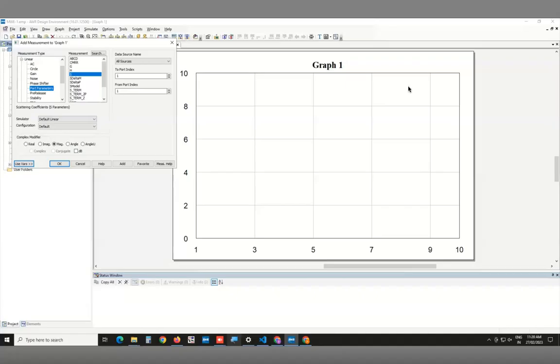Right, this is the same gamma, which for a simple case of just a load and a port is just Z minus Z0 over Z plus Z0. Right? We had looked at this early in the class, where Z is now the load impedance, Z0 is the port impedance, and this is the reflection coefficient. So this is the full complex reflection coefficient formula. If Z, Z0 are written as complex numbers,